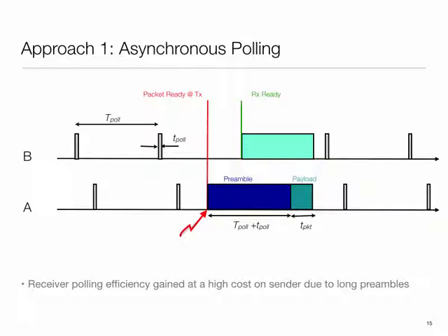You don't want that. We can make it more complex until it takes the ID value. Well, yeah, the thing is, the way the radios work is, either you're detecting something or you're detecting just energy. The moment you're saying I'm going to detect an ID, you basically have to have a demodulator and stuff like that. You could have a simpler one, but you'll have to have something. So all these obvious combinations unfortunately run into these problems: either you are going to be having a complex radio or you're going to be waking up falsely a lot.